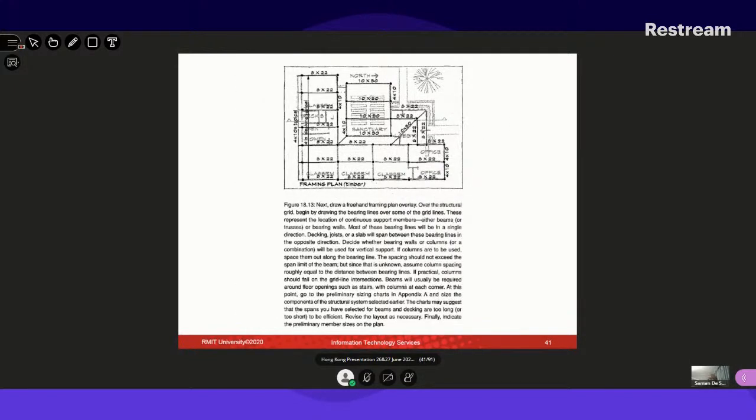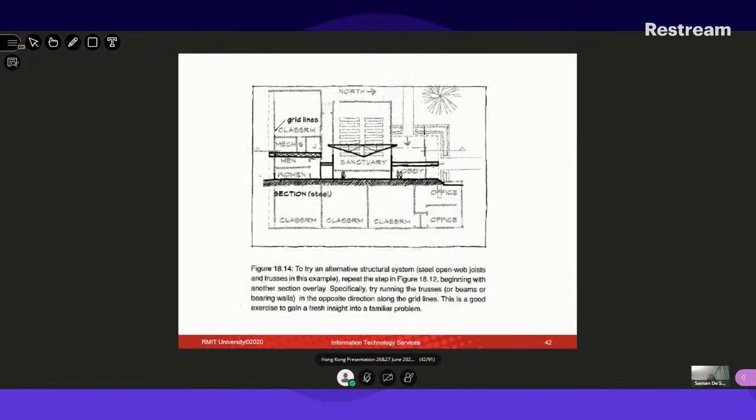So then only the structural drawings come into play. Oh, what is the size of the beam? Is this a secondary beam? Is there a column here? Kind of a thing. But in your case, not. You have all the walls around it, so that you can really support your beams and slab through those shear walls, which are quite capable of carrying vertical loads as well as lateral loads.